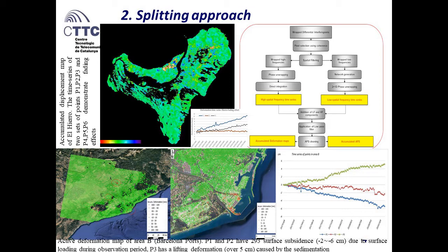According to the InSAR principle and frequency spectrum analysis, the interferometric phases can be divided into two parts, high frequency and low frequency. The approach proposed here is to split the consecutive wrapped interferograms into low and high frequencies. The noise and the deformation phase are retained as high frequency segments and the atmosphere as the low frequency segments. An empirical threshold frequency is used in the Butterworth filter to separate.